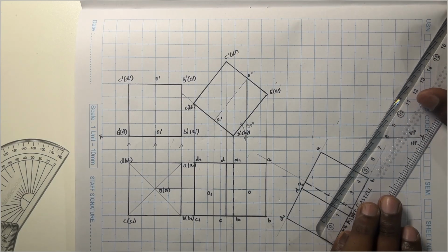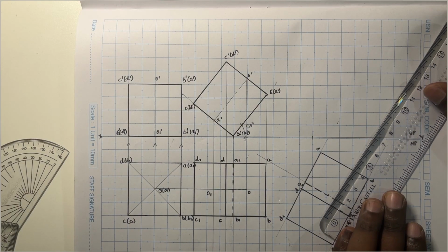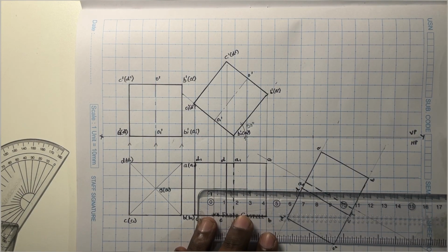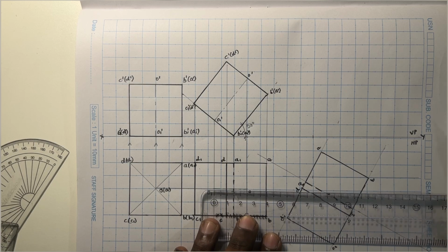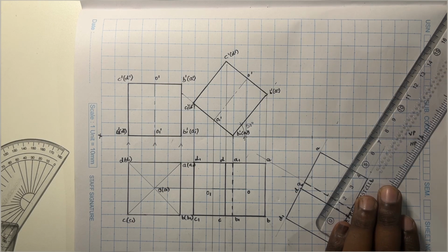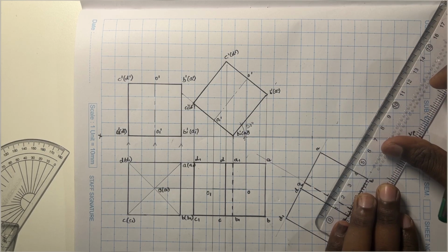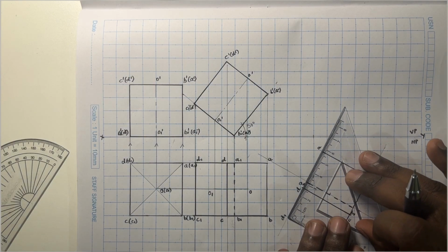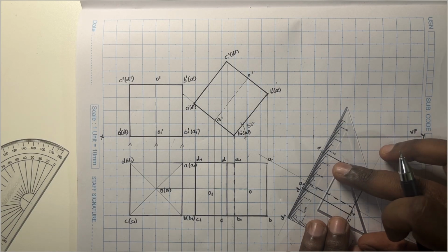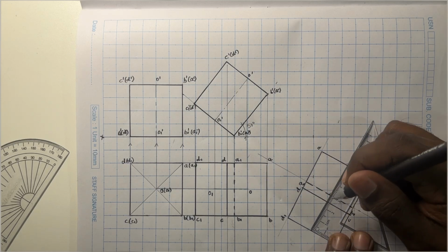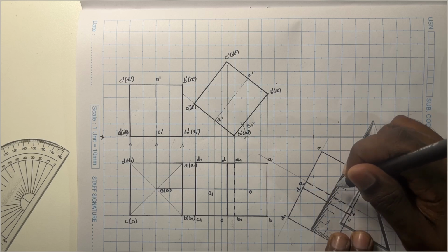So keeping the center point at 1.5 mm, I'm going to draw the axis length, which is measuring a total of 2.5 mm. Let me use the same color to show the axis. If you're not comfortable with the scale, just use a set square to make a perpendicular or a parallel line. Just keep your set square like this and slide it. So it is 2.5. I'll take one reference point.